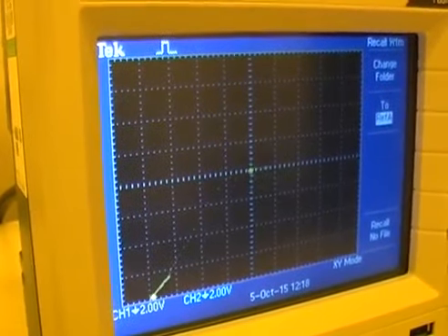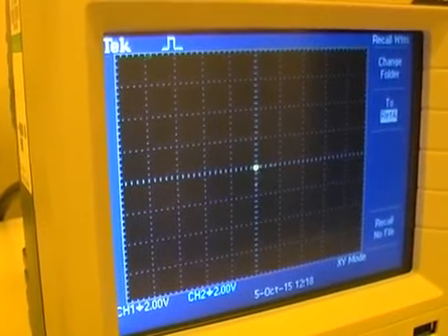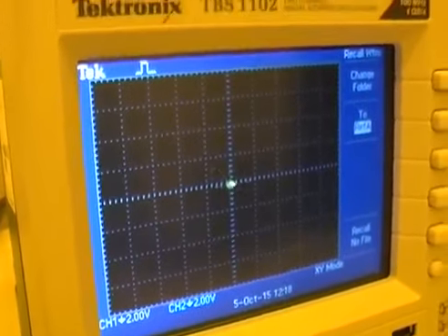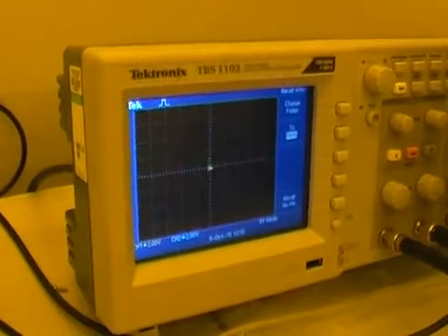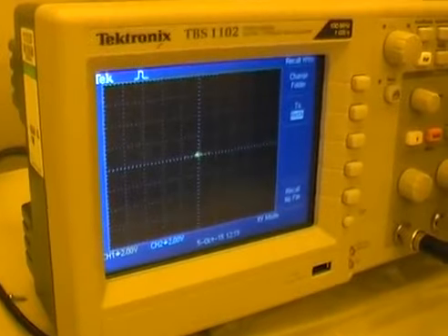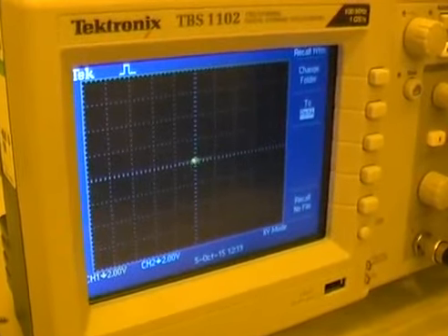The stage movement is monitored by a laser interferometer and is accurate to a few nanometers. And so this process enables you to calibrate the size of your main field to within a few nanometers. And this is what gives you good stitching. So all these calibrations are important.